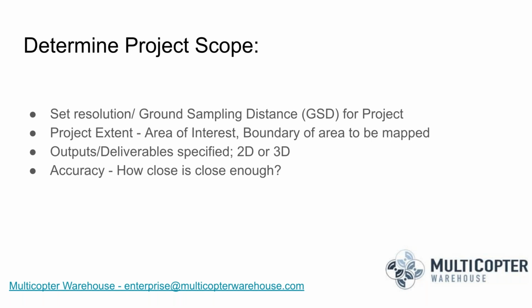I've even used a DJI Spark before. With the DJI line of drones, they have the ability to turn on a rule of thirds grid on your display or on your controller that gives you that tic-tac-toe crossed line pattern on your screen. That effectively divides your screen into 0, 33, 66, and then 100, or roughly 99% of the image. So as you're flying your drone forward, as you see an element come into the top of your screen and progress down, if you snap a photo as it first comes into view, then as it comes down to that first third line and that second third line, and then again before it falls off, you will be able to achieve roughly 70% overlap and be able to get a successful reconstruction.